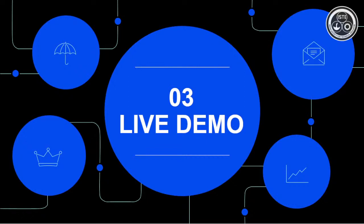Now for printing the value, just call Serial.print, give a string like "Temperature", give a colon, and I am just copying it. Here I will be printing the argument t, and again I will be using Serial.println, because after this line it should be on a new line.